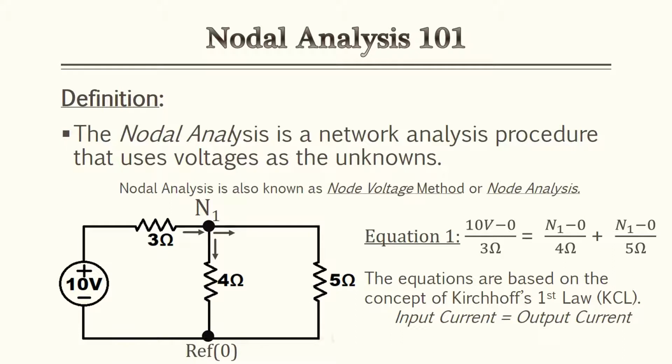Now, just be aware, in electrical engineering, node refers to any point on a circuit where two or more circuit elements meet. So be aware, if you have a right angle or anywhere that's not considered a node, you can't count that as a node. It must be where two or more circuit elements meet or two branches off.